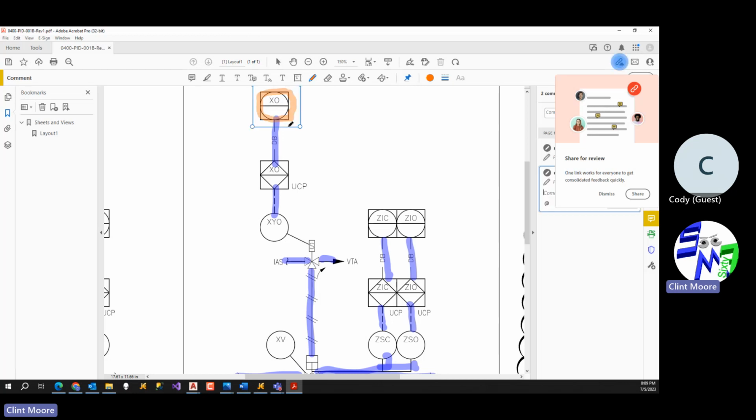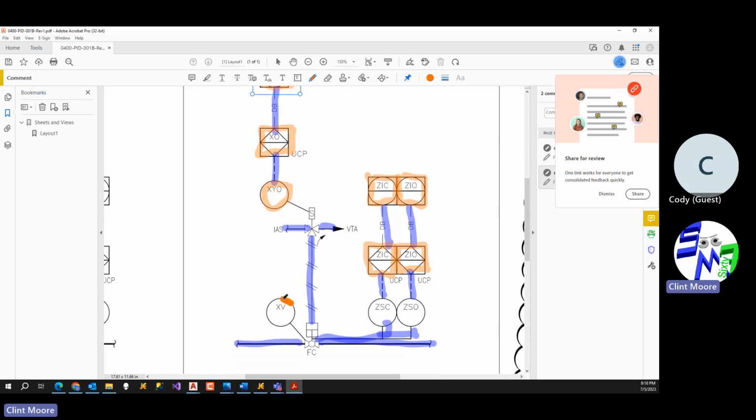When you have symbols, they're going to be a standard size, okay? And you want to work with these standard sizes, so you want to make them a block, all right? That's the first thing Brandon did: he made these in blocks. He made them attributed blocks as well, and you kind of see what they are. So you essentially have three different blocks that all come together here.